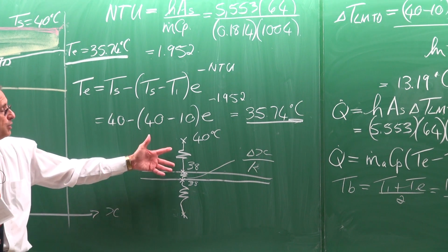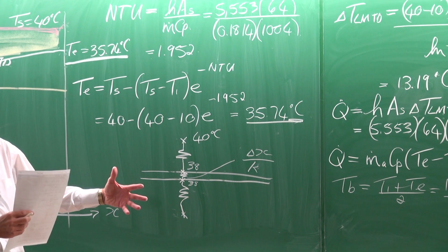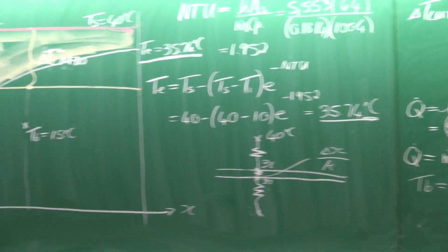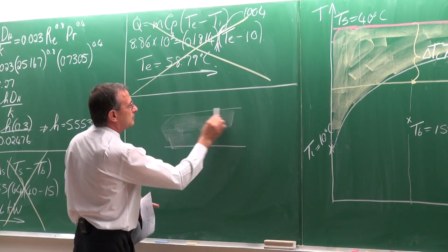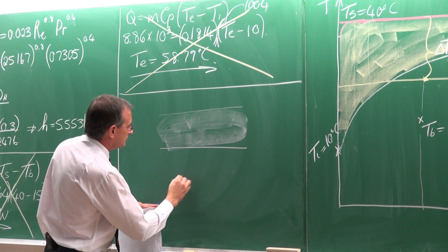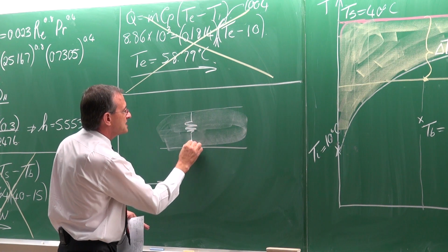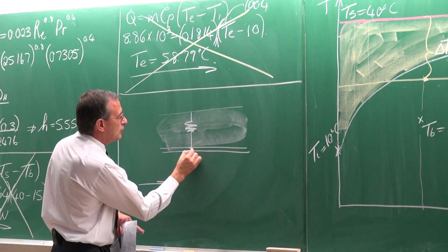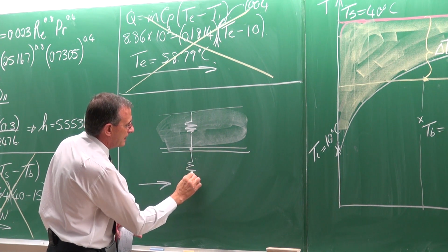It's the same principle now with insulation. So if you want to insulate this duct, let me draw it here. Let's suppose here's the insulation material, and here's the air going through there. Then again, we've got the resistance terms for the insulation material, for the galvanized steel or the plate, and then for the air.